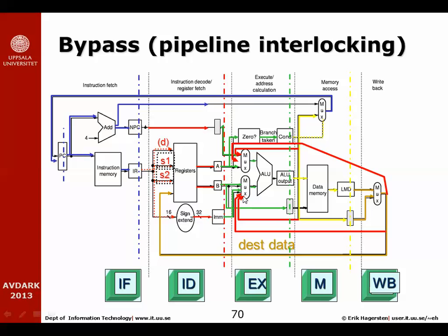If the hardware has detected that we have this kind of hazard going on, then it will choose one of these two bypass paths to feed the ALU instead of the normal green arrows. Likewise, we have another two bypass paths going to the upper mux, so both these muxes would now be four-way muxes. Typically they would be controlled by some piece of hardware that would detect that something went wrong.